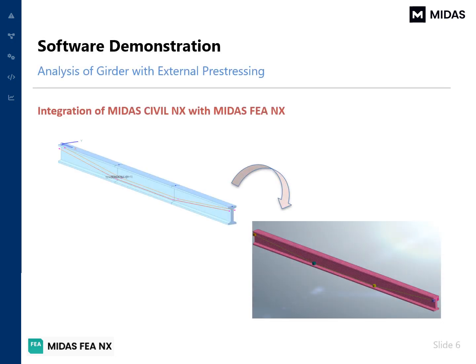During the demonstration, we will discuss how to model particular tendons with deviator blocks, how to apply the prestressing force, and how to consider the connectivity between the newly added members and the geometry imported from MIDAS Civil NX software. Along with that, we can also simulate the construction stage analysis, addition of the reinforcements, and whether the structure needs to be analyzed with nonlinear or without nonlinear parameters.